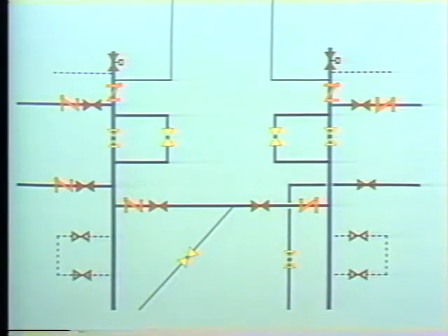Well, our piping print is beginning to take shape now. We have the pipes to transport the fluid, the valves to control the flow. We need to add a couple of pumps here to provide the force to push the fluid through the system, a couple of strainers to filter the fluid, instruments to indicate temperatures and pressures, a reducer here to step down the size of the pipe for a sampling line, and we have a pretty representative system.